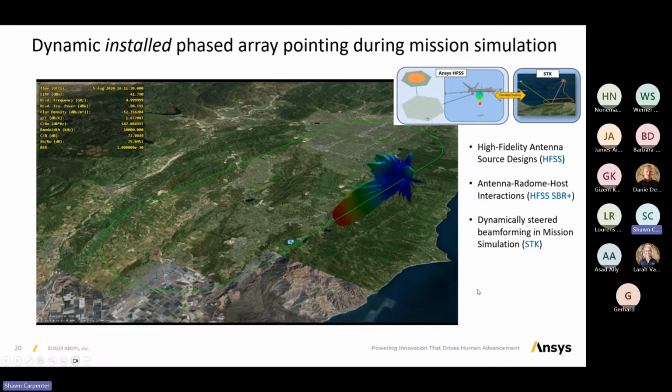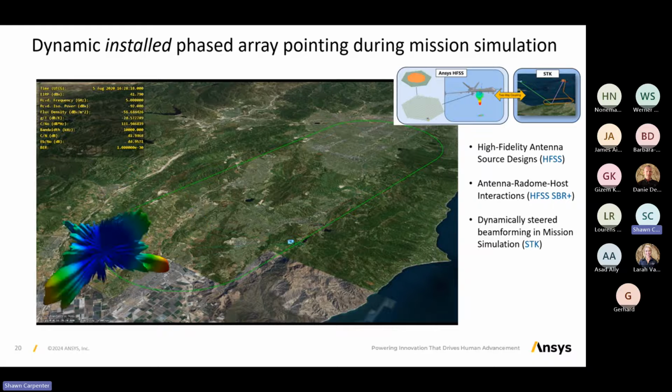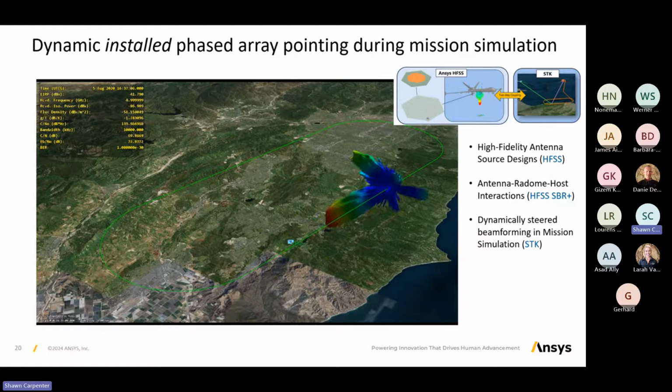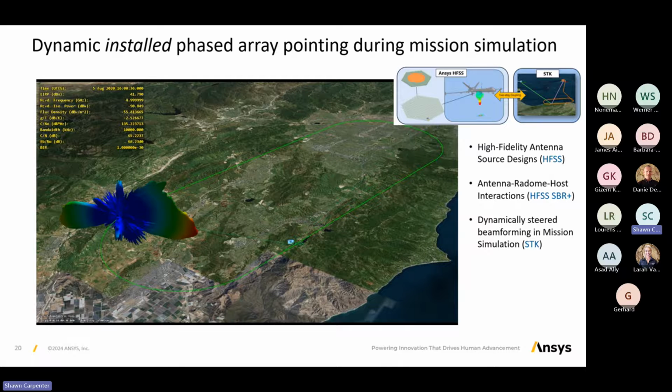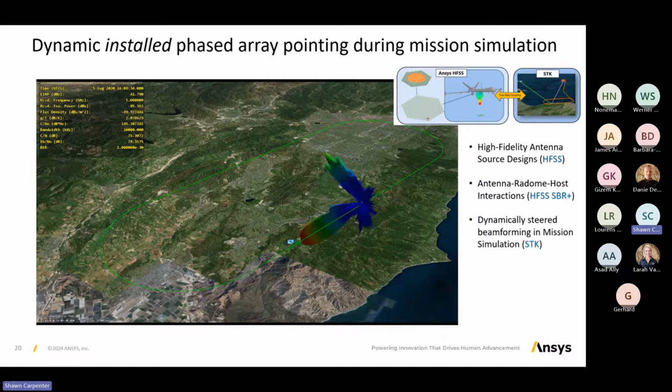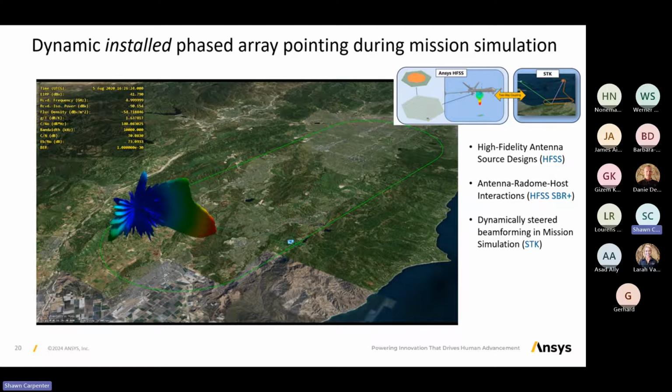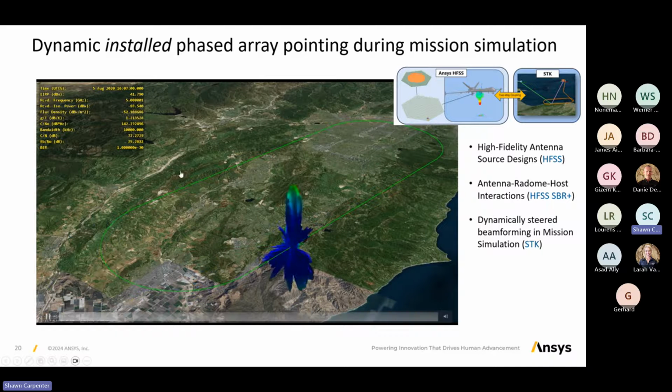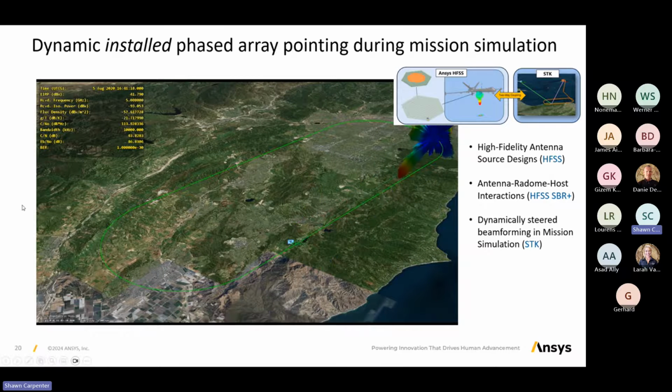And that's because as the aircraft goes through those corners, it's banking. It's giving the aircraft a bit of a roll. It brings the near side wing down closer to the base station, and that gets into the field of view of the main beam just a little bit. So you can see a spoiling of the main beam as we get down close and the dipping of when the aircraft dips its wings. You also see other internal reflection effects of the radome and other coupling effects that are manifest as this thing flies. And then, of course, in the system simulation, you can continually monitor things like the carrier to noise ratio or the bandwidth, the carrier to noise, Eb/N0, bit error rate, and so forth for the link.